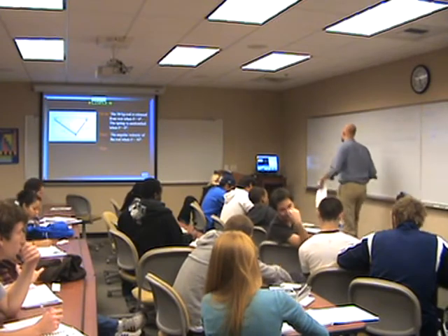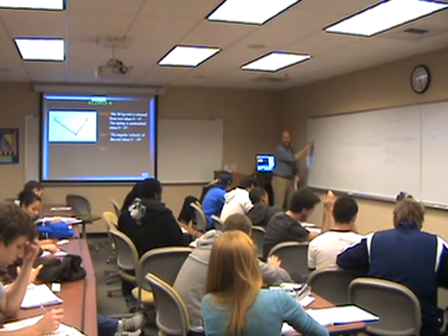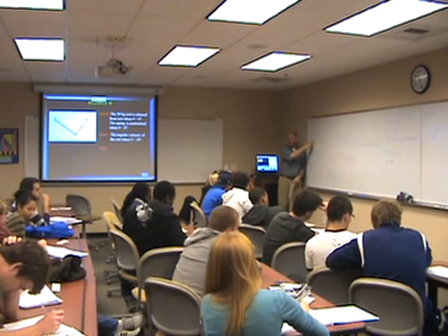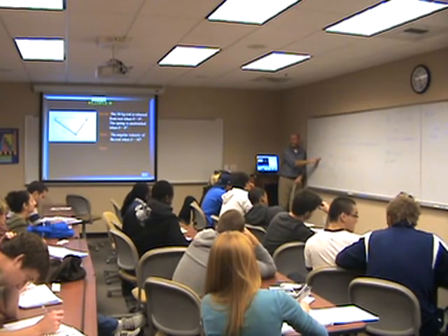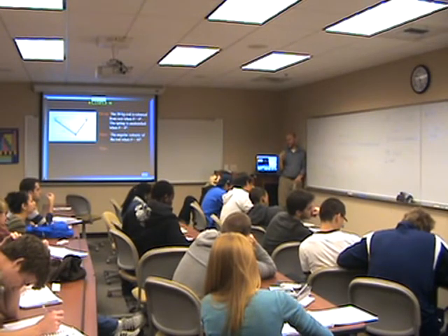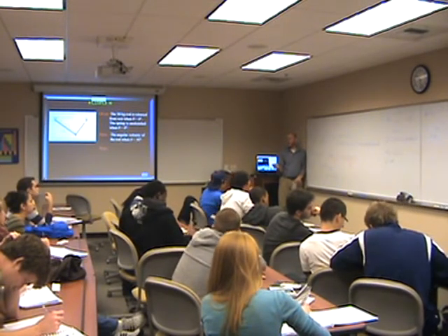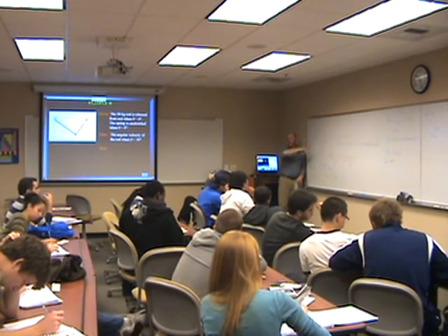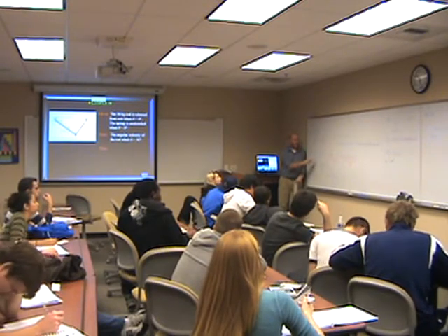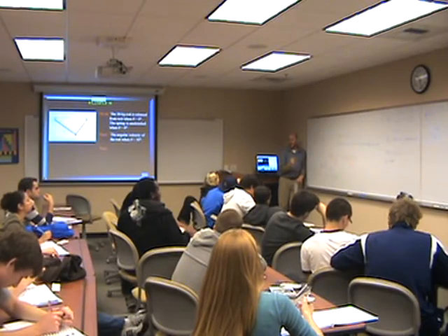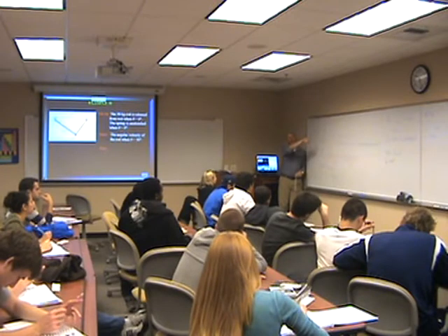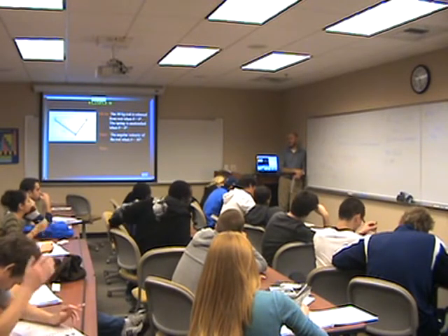So in this case, we could use I about our fixed point right here, but that's not in the table, so therefore we went with I_G. This always works. I_O is a special case that works for a fixed point at that instant, or for an instant center, but here the instant center is moving around and it's complicated, and it's not in the table. So we would have to use the parallel axis theorem to find out what I_O is. That would come out the same though. It would come out the same, yeah. If you have a fixed point, I_O is in the table, and then you can just go for it.